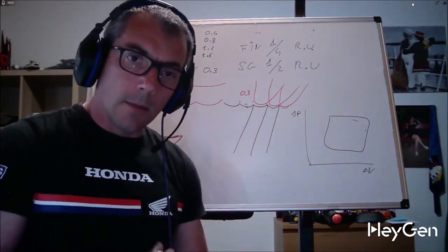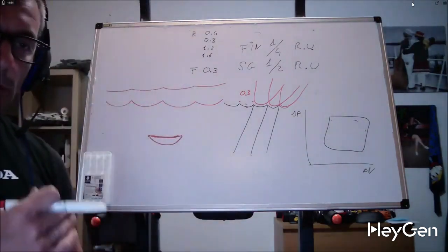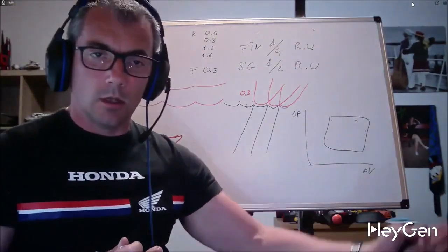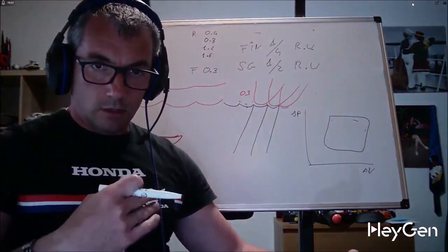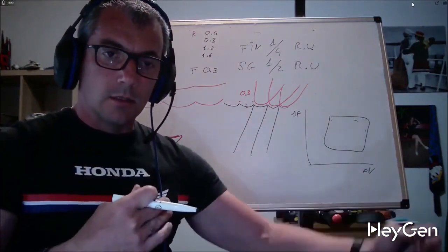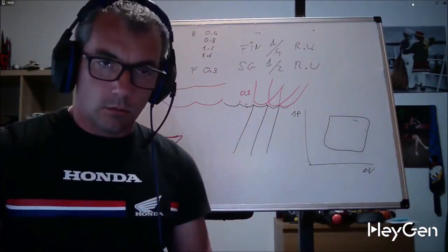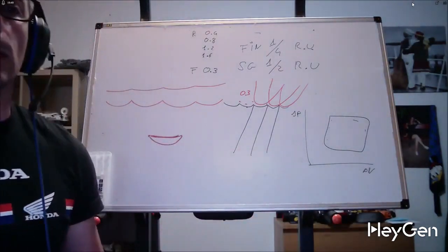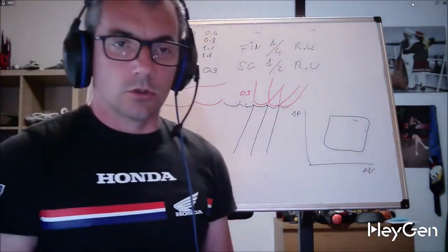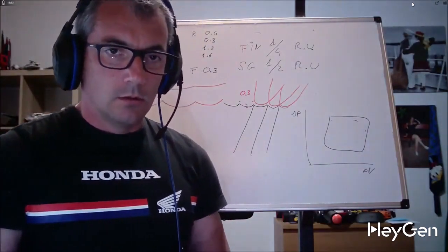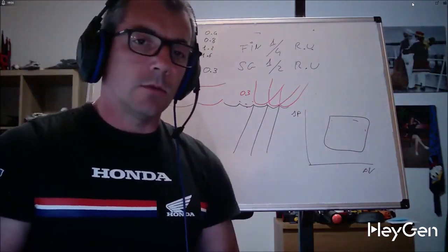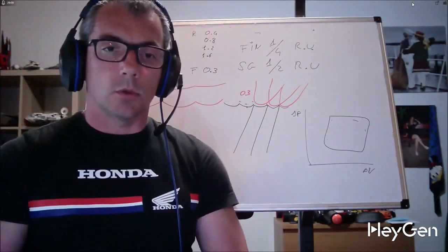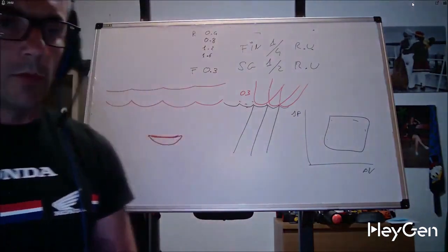So that also needs to be done. I want to establish that a user should work for 15 minutes rather than 25 pieces. I check the roughness from the first to the last and standardize the duration. So, if I require a roughness of 0.8, I will need to start at 0.6 to reach 0.8 in drift. Here lies the difference between the inexperienced person who wants to be a turner and the professional who wants to deliver always compliant pieces.